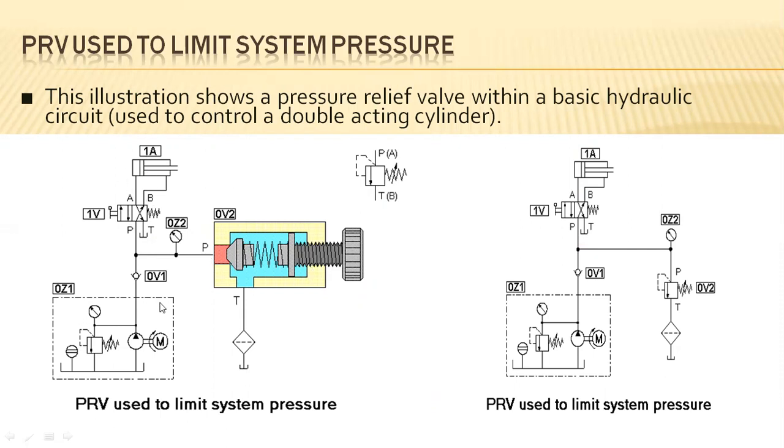operate this actuator with the directional control valve. If the plunger is in the first switching condition and moves in the forward direction, that causes compression in the spring, causes this motion, that is, the fluid will enter the first A channel and cause the forward movement and release towards the left side direction. And this is the condition here, and it releases to the oil reservoir.